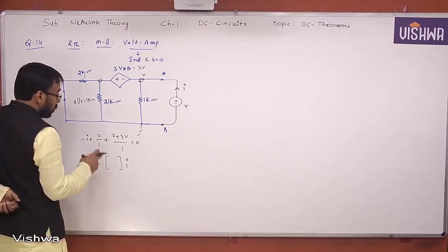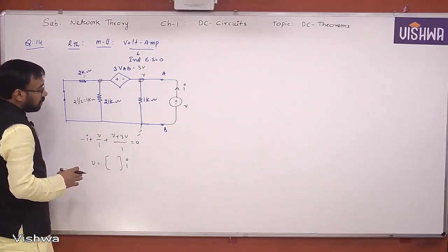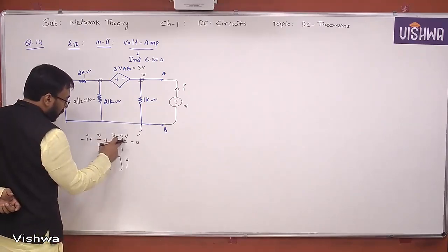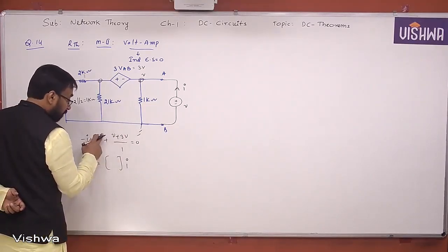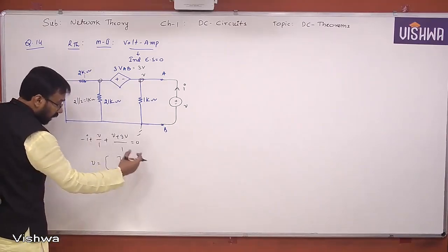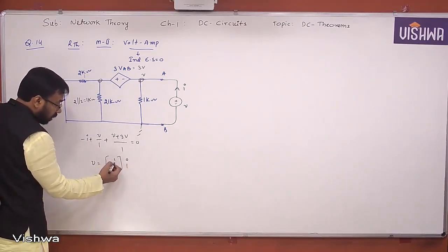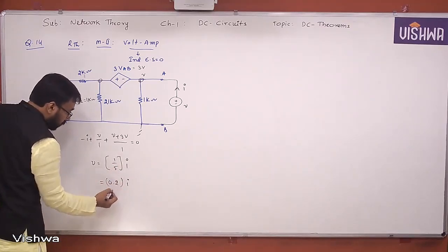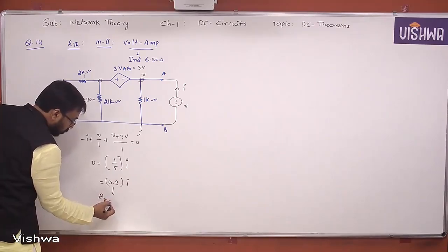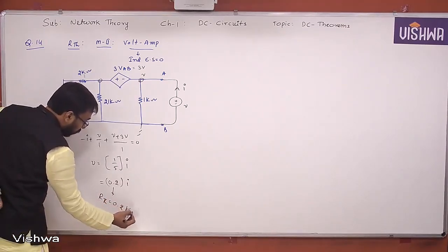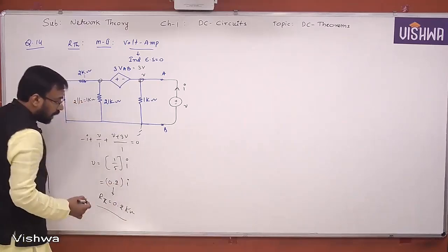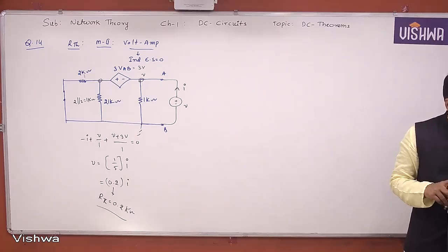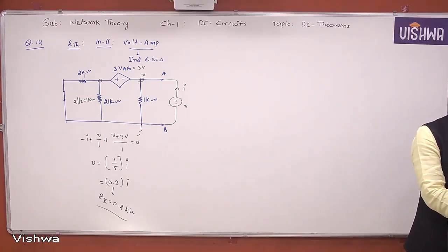Understand all of you? So this is showing clearly that already this is V plus 3V, this 4V plus V, 5V. So 5V is equal to I. Then V is equal to 1 by 5, nothing but 0.2 into I. So this is nothing but RTH, 0.2. We are taking kilo ohm because current is in milliamperes. So you got the same answer, 0.2 kilo ohm, in the previous case as well as this case. Please note that down quickly and we'll move on to another problem.